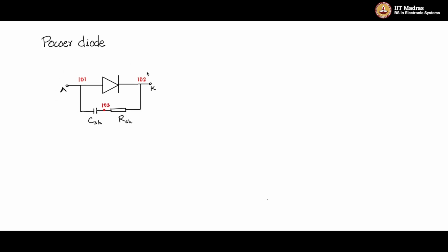So first let us have a model for this. In order to have a model, I will open a sub-circuit. A sub-circuit is a subroutine type of template in Spice which can combine several circuit components in the form of a circuit into a single module. So we will use that sub-circuit template. The sub-circuit template has a reserved keyword, .SUBCKT. And now I will describe this netlist in the sub-circuit.